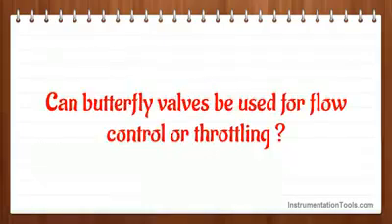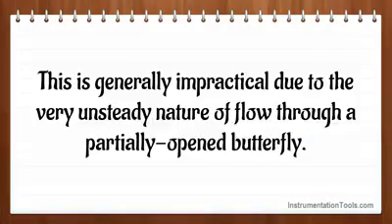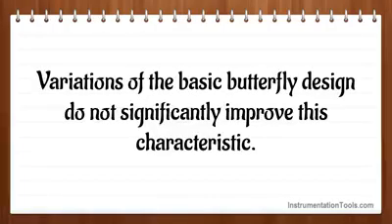Can butterfly valves be used for flow control or throttling? This is generally impractical due to the very unsteady nature of flow through a partially open butterfly. Variations of the basic butterfly design do not significantly improve this characteristic.